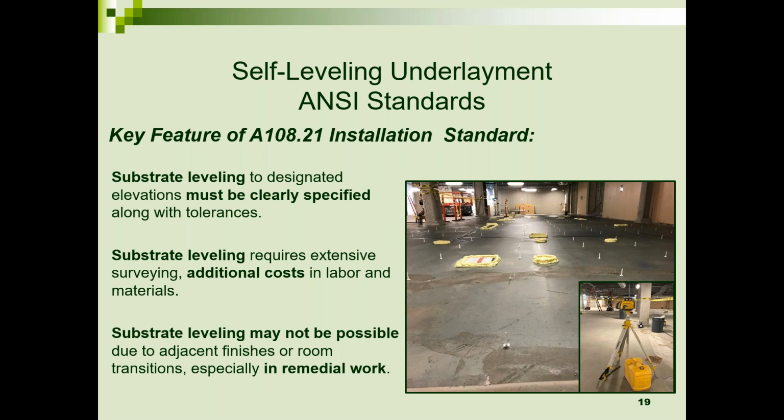And I bring this up because if you're a contractor looking at quoting a project and they specify leveling and you throw out a bid for flattening, you're not going to have enough money in that job to do that correctly. Or if you're a specifier, you need the floor leveled, but you only specify flattening, it's not going to get done until someone comes up with more money for that contractor. So flattening and leveling are two different end results. Understand the difference when specifying or bidding a project.